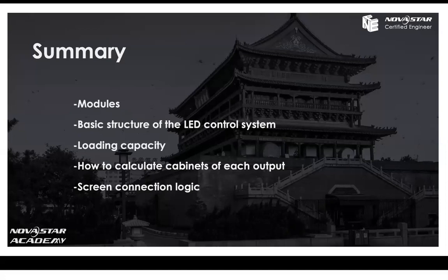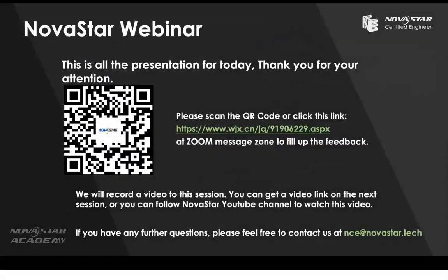Let me do a summary. Today, we have learned the smallest units of the LED screen, modules, the basic structure of the LED control system, and also how to calculate the loading capacity and the screen connection logic. All these are very useful information and knowledge in this industry. Hope all of you could get it. Okay, that's all the presentation for today.